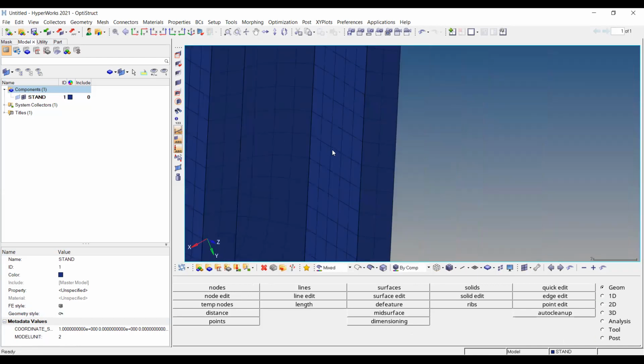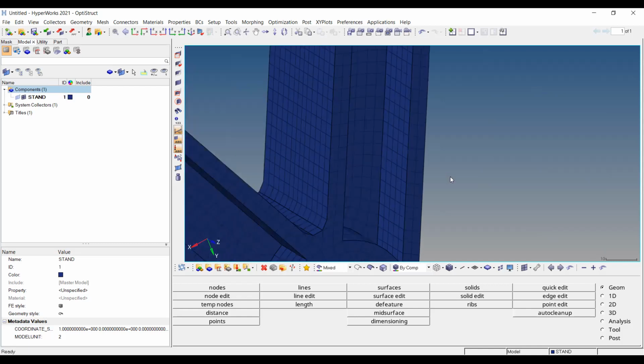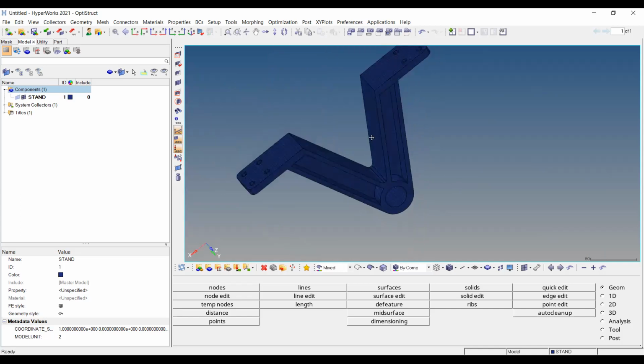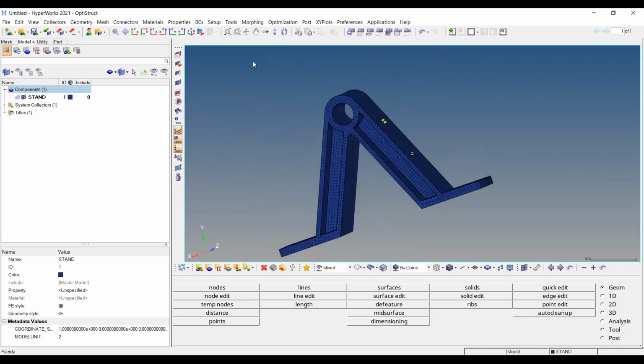Whereas in module 2 for the triangular element, we used a 3 noded element and a 4 noded element. Likewise, in hexa also there are different shapes, but the hexa, penta, pyramid and the tetra are all 3D elements, only with different shapes. Observe what terminologies we are using, so that it will be very easy to understand the things. We'll see how the tetra elements look like. I'm showing it in a different HyperMesh.